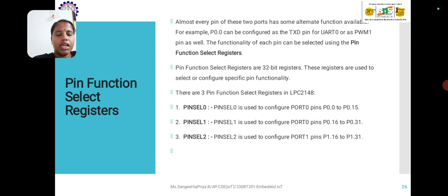PINSEL0 is used to configure port 0 pins, that is P0.0 to P0.15. Next one is PINSEL1. PINSEL1 is used to configure port 0 pins, that is P0.16 to P0.31. Next is PINSEL2. PINSEL2 is used to configure port 1 pins, that is P1.16 to P1.31.